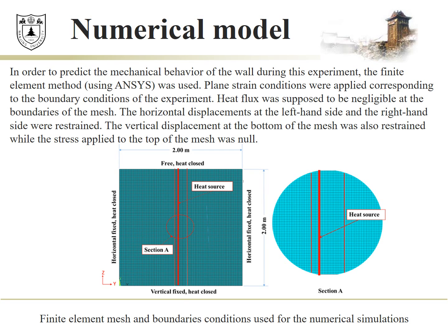In order to simulate the heating phase performed in the experiment, the temperature of the pipes was imposed. The initial temperature of the whole system was first fixed at 10 degrees. To start the heating phase, the temperature of the pipes was increased from 10 degrees to 48.5 degrees in a curve during the first 20 hours.